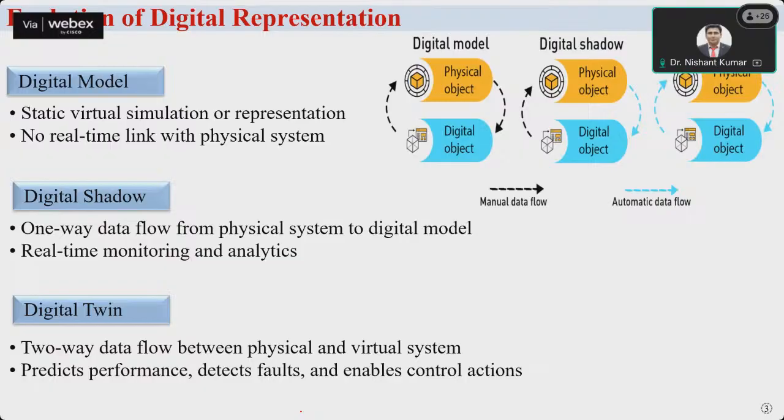But suppose you are going to do these things by using the digital model, then what will you do? Simply you will simulate the system in your MATLAB, and then here you will see the KP, KI, and then you will use these in your hardware platform. But yes, this will not work there. Definitely these numbers are not going to work exactly, but this is very clear. Those numbers that will work there will be close to this. Means a rough idea you can get from that, means KI will be 1 or maybe 100 or 0.1.